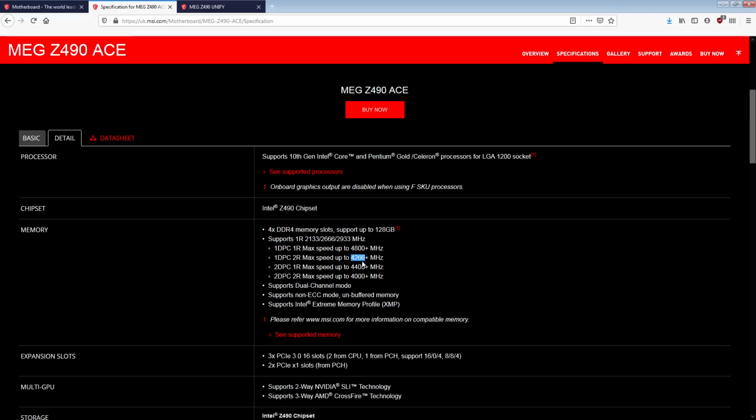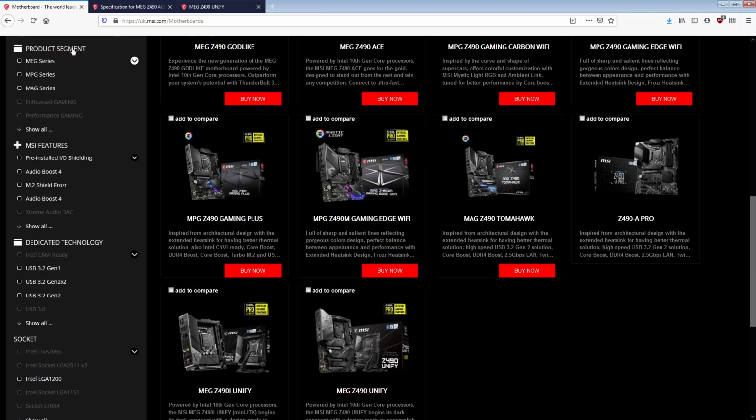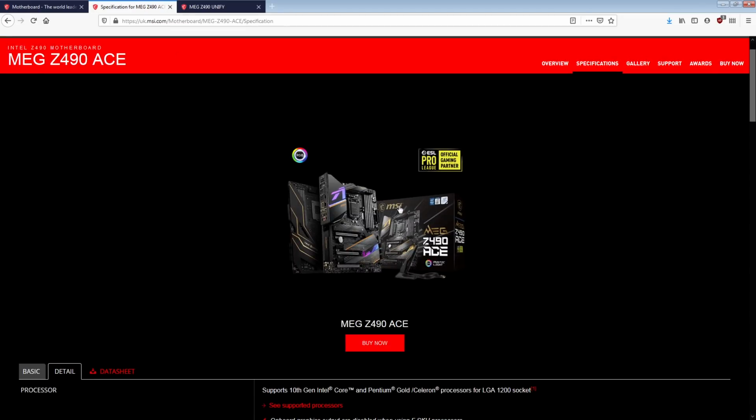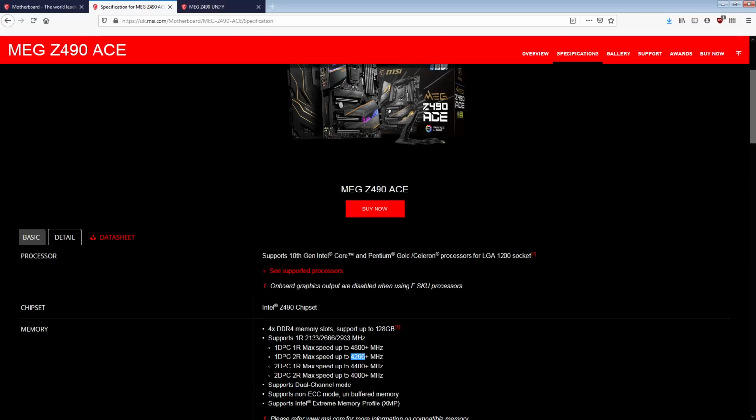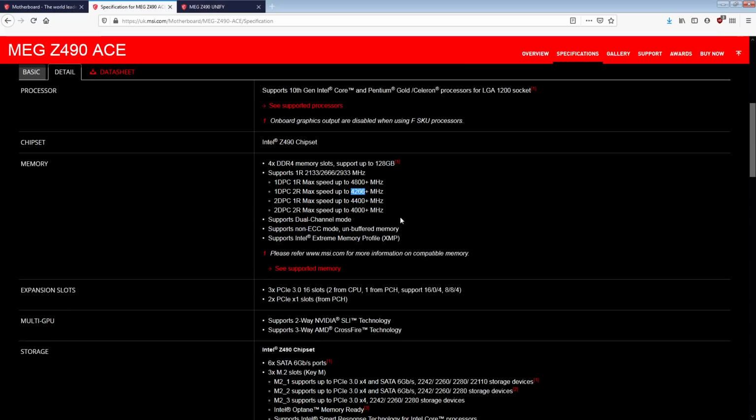It's interesting that the 2x16 setup would be weaker, because this is a daisy chain topology. Like, MSI for Z490, all of their boards are daisy chains. They all use tabbed traces. There are differences in the layer counts. Godlike is an 8, this is a 6.